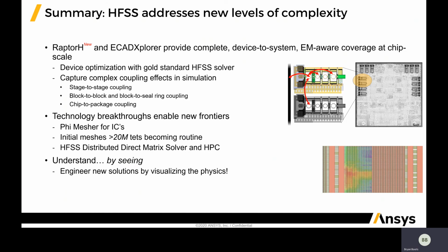And it's to the point now where with 2020 R2, we're seeing initial meshes in excess of 20 million tets becoming somewhat routine. And if we think back to that first slide I presented, the idea of meshing 20 million tets or a single block or multiple blocks using HFSS gold standard solver technology with no compromises is mind-boggling, and it's very exciting.